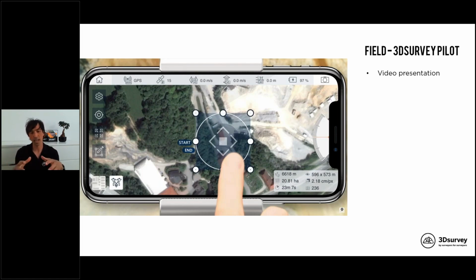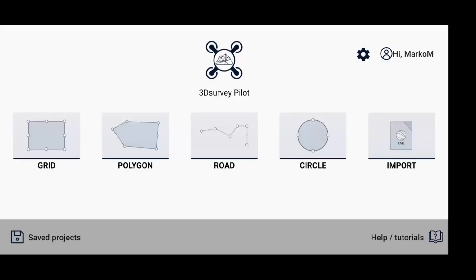And what we figured out is that the most effective way for small accident sites would be to do 3 circle flights with different camera angles at different heights, and the circles should have different radii. And I actually prepared a video for you. Just a second to roll this video, so that you can have a feeling of how to plan the mission to capture the best images for the best 3D models. So here is our video.